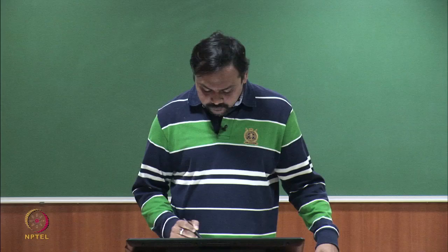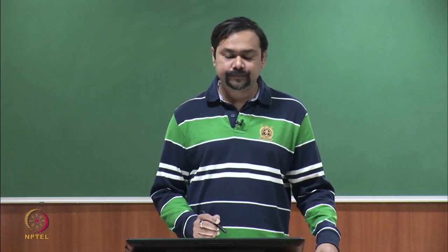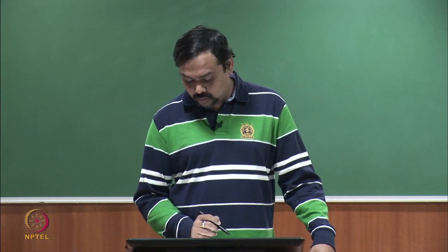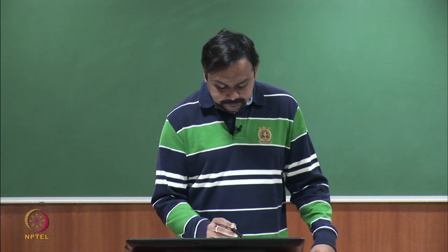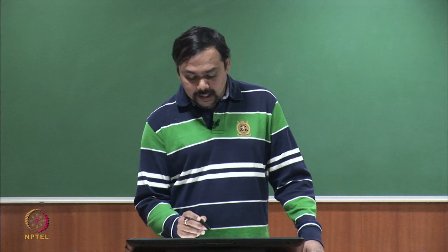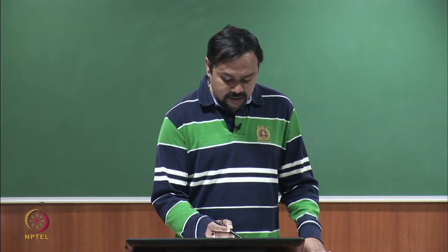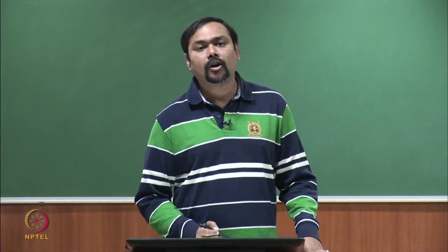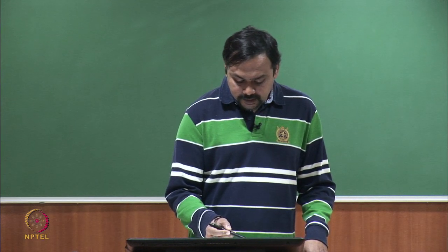So, this is what we are summarizing here, and based on the table which we have shown, we can see that in this converter S1 is S3 complement and S2 is S4 complement. So, these two switches S1 and S3 are given complementary pulses, whereas S2 and S4 are given complementary pulses.